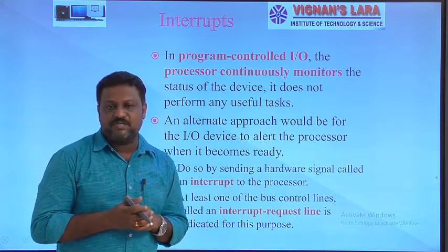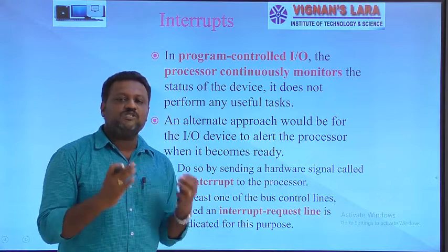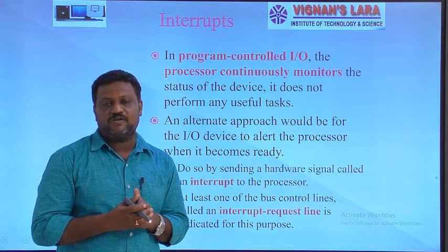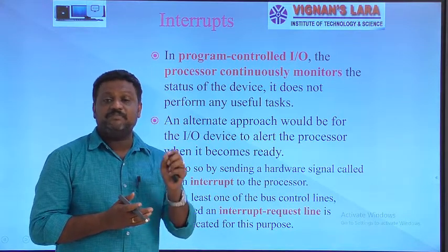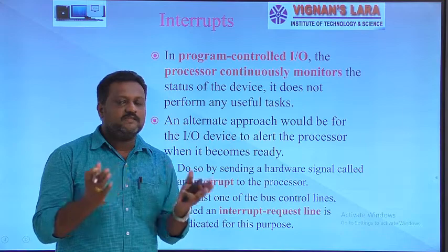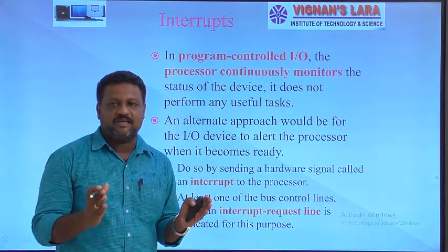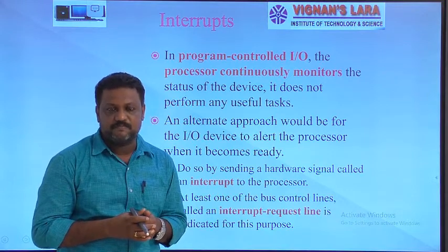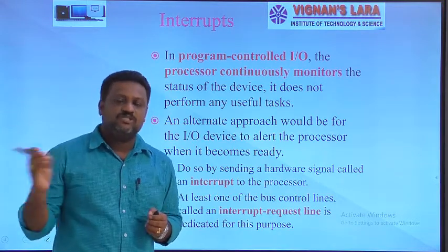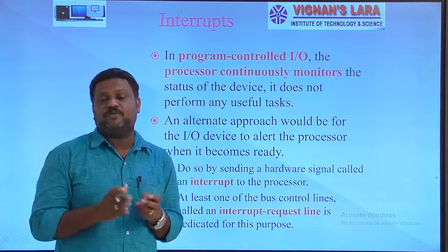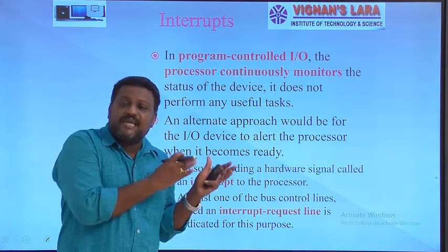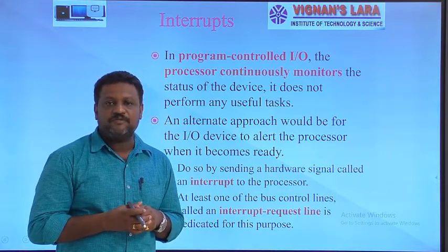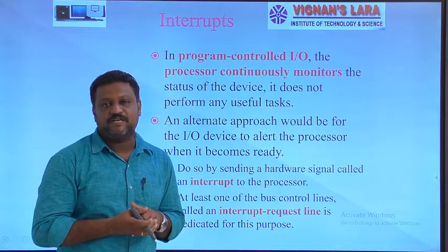Due to that, in the previous case our processor was continuously monitoring, or repeatedly verifying, the status of the I/O device. Here time is saved, because the CPU doesn't have to wait or check the status of the I/O device at regular time intervals. In this case, the CPU can do some other task which is useful, that means the CPU can engage in some other data processing function instead of repeatedly verifying the status of the device.